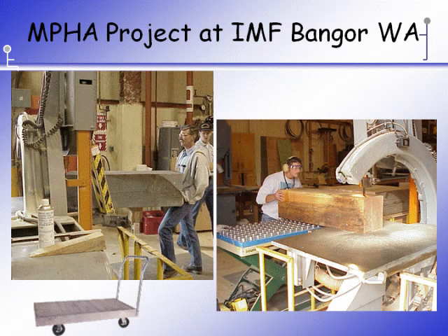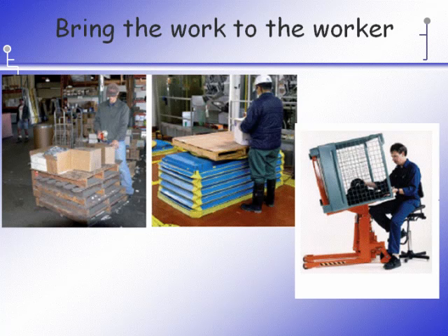They're able to push the keel block from the platform truck onto the roller transfer table, raise it up to the height of the scissor lift table, and now push it through the band saw without having to support that weight. They're able to do more true cuts, as in increase their accuracy, and when they got so far forward that they were reaching across the scissor lift table, they use a push stick to push it the rest of the way through.